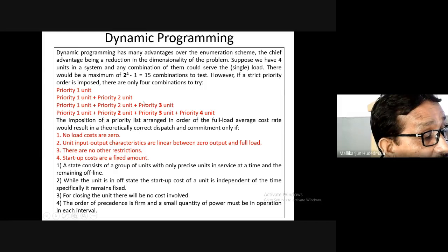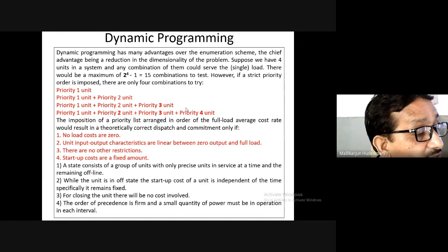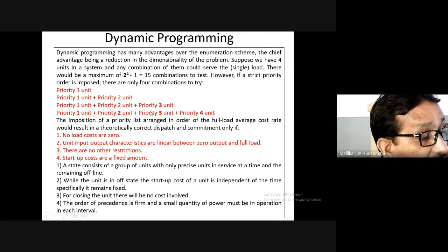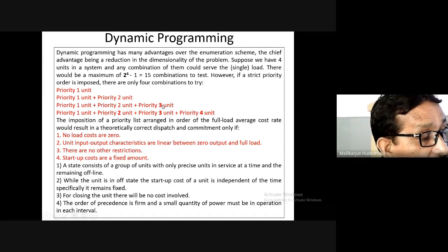What was your previous decision? The previous decision is unit number first choice and unit number second choice, together fulfilling 200 megawatt. Now that is your previous decision. On the outcome of that decision, the 3rd decision should work such that its output is optimal and best to go for the next stage. Then you combine one more generator to the previous decisions, so decision number 1, decision number 2, decision number 3 have come. These 3, suppose 100 megawatt each, will carry the load up to 300 logically.